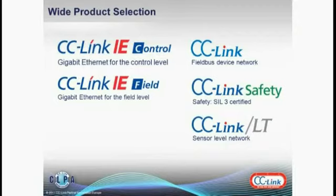So this slide gives you a breakdown of those 2 networks in terms of the technology they actually use. From the Ethernet side of the technology, on the left side, we have CC-Link IE control, which is a gigabit Ethernet technology used to link controllers together. And then below that, we have CC-Link IE field, which is also a gigabit technology, but is intended for the connection of field devices to controllers. And the important point here is that both of these networks use the gigabit Ethernet technology. This is something which is unique on the market at this point. There are no other open network technologies based on Ethernet which operate at the gigabit level.